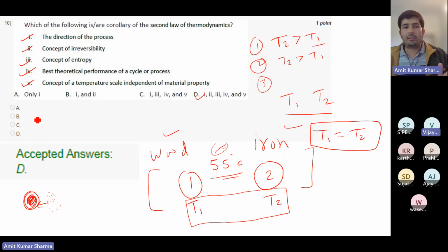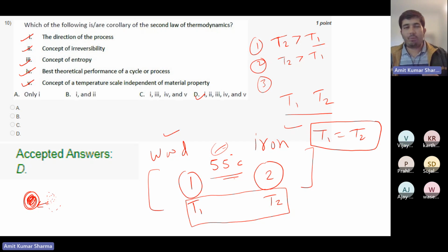In this way, you are telling that the rate of heat transfer in the iron chair is greater than in the wood. That's why you feel the immediate effect. Yeah, right. Because in the iron chair the conductivity is higher, so the rate of heat transfer will be higher. Okay, so you know the answer, but you are interpreting it wrong. Both temperatures will be the same. It's only about feeling, because it's only about the heat transfer, the transient heat.